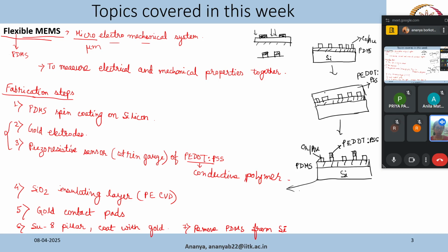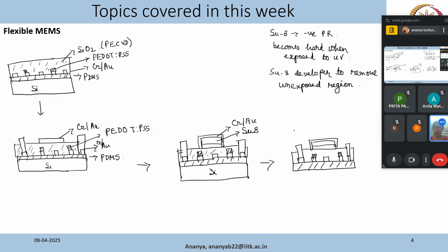So here this is 1, this is 2, then this is 3 to make the contact pads, and after that to make the SU8 we don't do the whole litho, but we can consider it. So 4, and then again to make this gold electrode. So 5. So we need multiple steps of photolithography. This is like the heart of microfabrication, and we often do it.